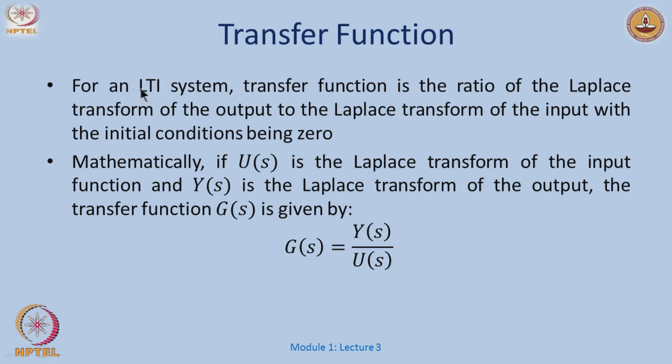For a linear time invariant system, let me also recollect that we will here focus on systems which are just single input, single output, also called SISO systems. For these LTI SISO systems, the transfer function is the ratio of the Laplace transform of the output to the Laplace transform of the input, assuming 0 initial conditions.